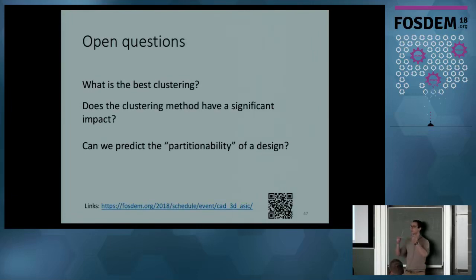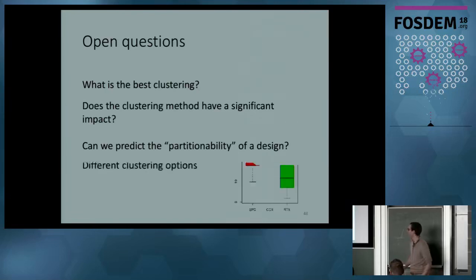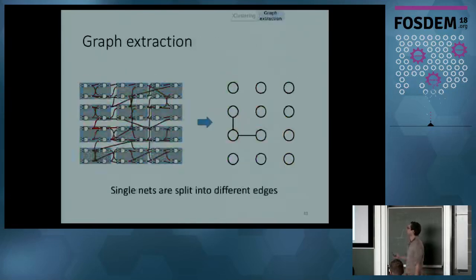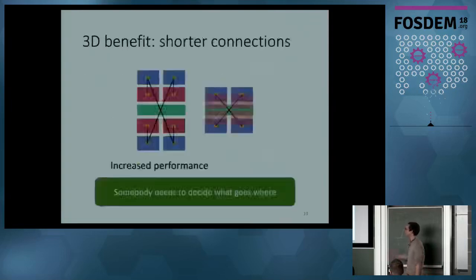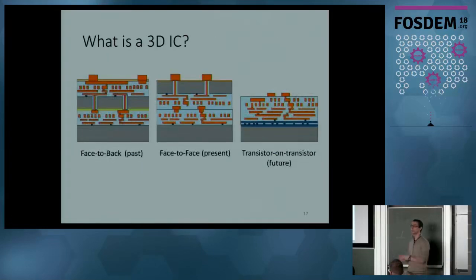Yes, actually. If I just go back to the slides, it would be easier for everybody to understand. When going 3D, you obviously have interconnections between the 2 layers, like here. And those interconnections are longer than the regular metal layers. So the one you have here at the front is longer than the metal layers you have here. We try to reduce the performance loss due to these longer vias between the 2 layers by cutting the longest nets, so that they would be shorter even when going 3D. You would otherwise have performance loss if you cut really short wires that would be elongated by going 3D, and we try to avoid that.